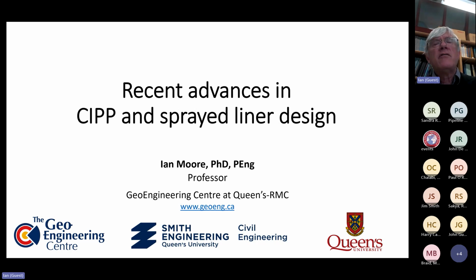If it does, then the solution we've got will not be conservative. So if you had slip, let's say for a gravity flow liner, that went beyond those points where you'll get that locking in of the motion, the solutions that we've presented to date will not be conservative. So it's like a lot of these things in research, we take steps forward, and that's as far as we've got. So I really appreciate your question, mate, because we need to be careful understanding that as we apply the design equation that I've presented today. Thank you.